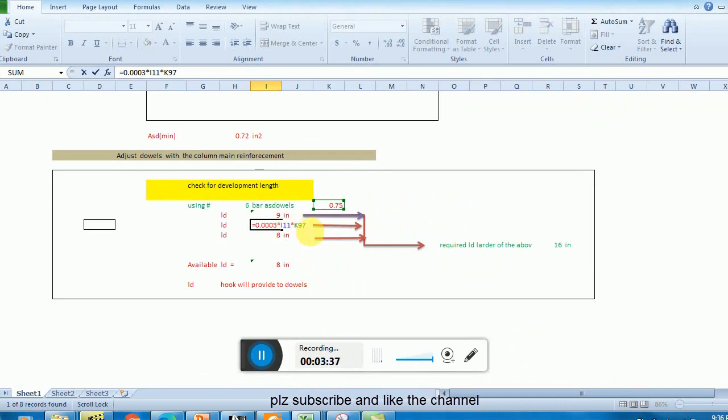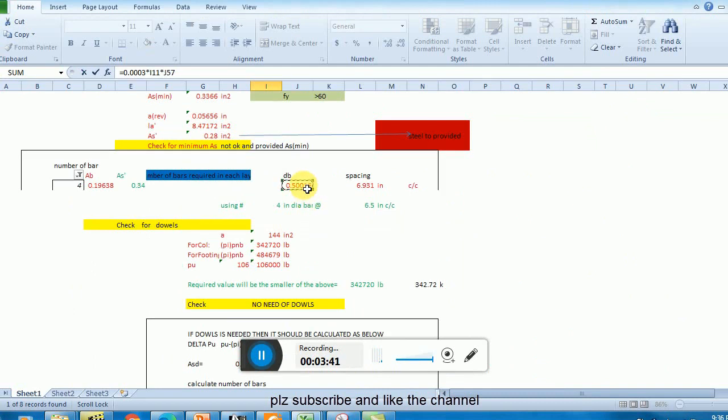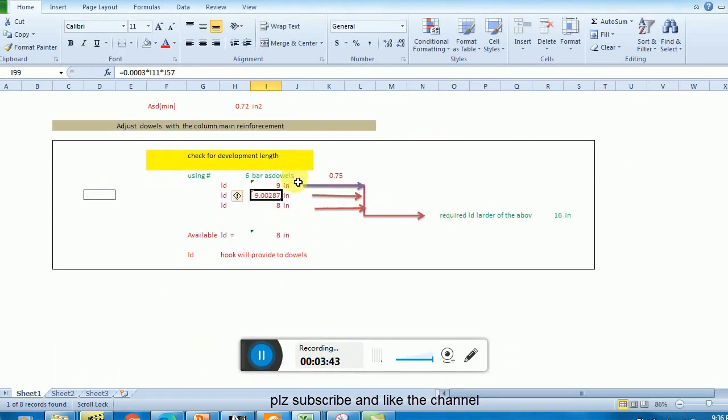So this is fy and this is db. Now I have to search for db, this one, and this is 9, and you round this. 8 is the minimum. You have to select the maximum value from these values.